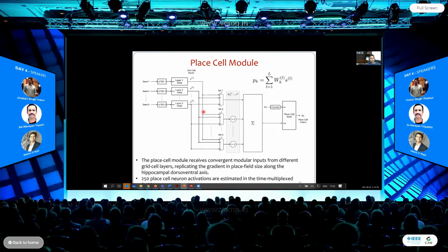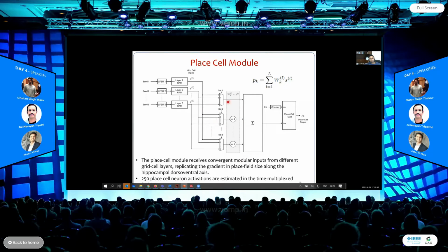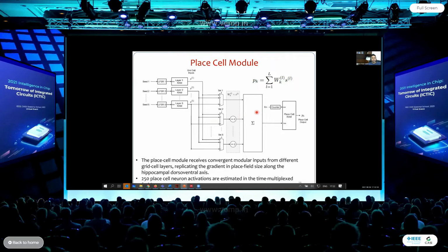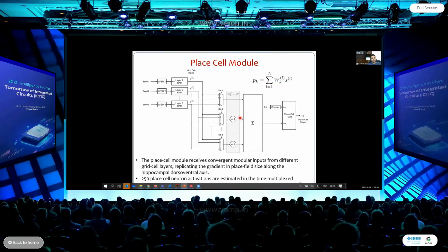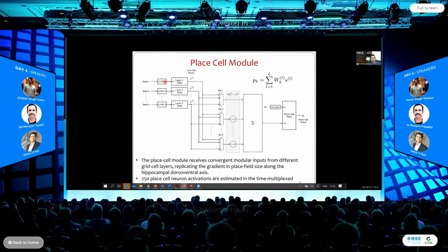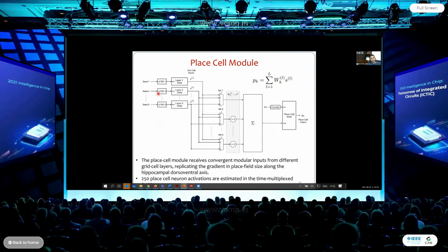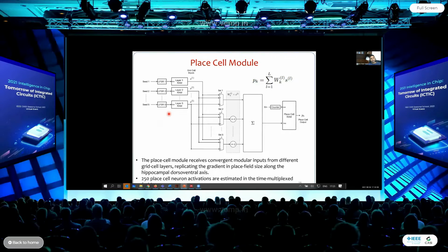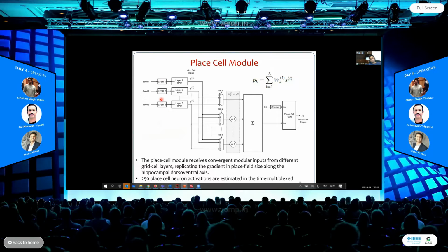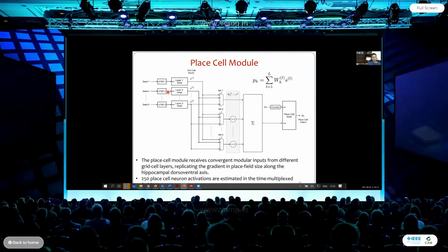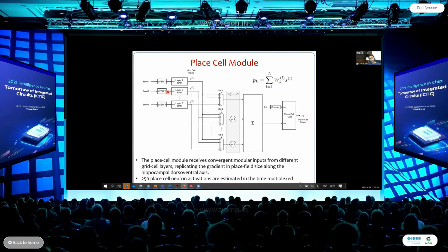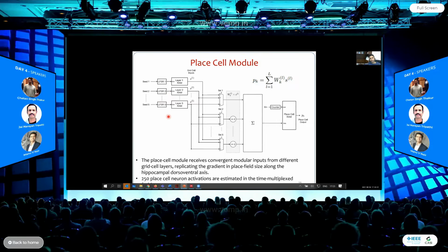So this is the whole architecture that I explained here, and we did some optimization to avoid multiplications and other hard operations, to reduce the complexity in terms of computational power and area. Instead of multiplications, we use power-of-2 shift operations, and we also use random number generation to select which grid neurons you are interested in. Based on that, you don't need to store the connectivity information. You just use the LFSR and run it with the given seed. Automatically, it will pick up the right neuron each time.